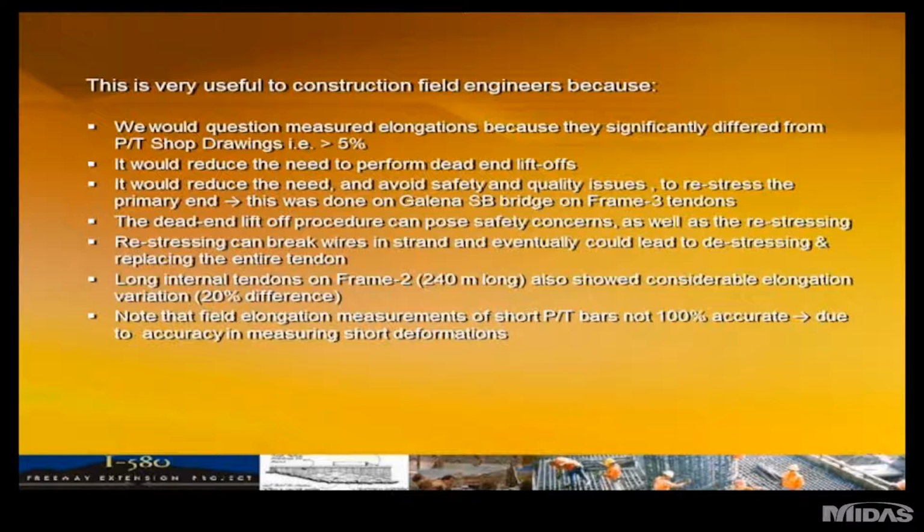Obviously, when you lift off and re-stress, depending on where the jack grips the strand, you can, like I said, break wires or strand. This structure was so sensitive that we could not afford to lose more than one strand. If that would have happened, then we would have ended up de-stressing many tendons in order to get what the designer needed.